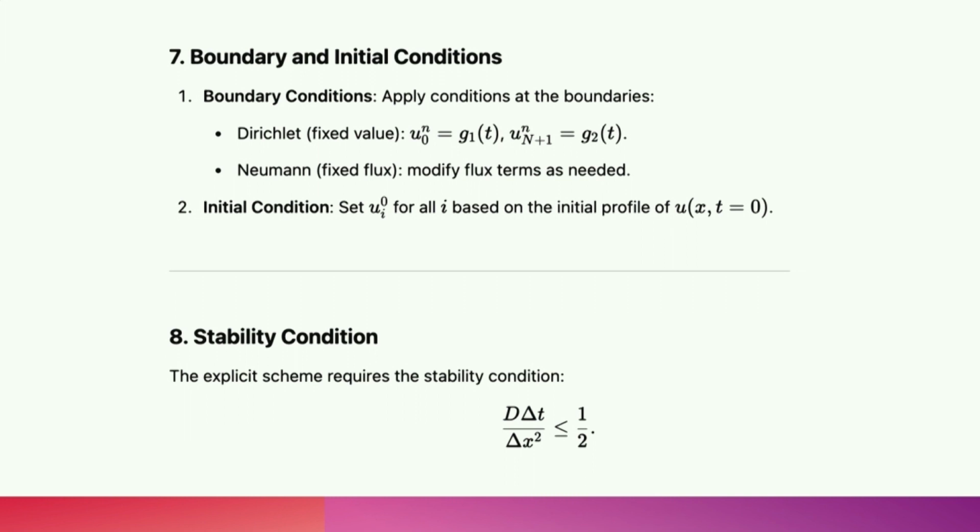For example, if it is some gray wall, then when it absorbs the sunlight, it can produce a heat flux. That heat flux can give us some heat, which is a rate of change of heat. So that means you have to apply the heat flux condition. You cannot apply the constant temperature condition because they are absorbing the heat. So here we can apply any one of these based on the reality.